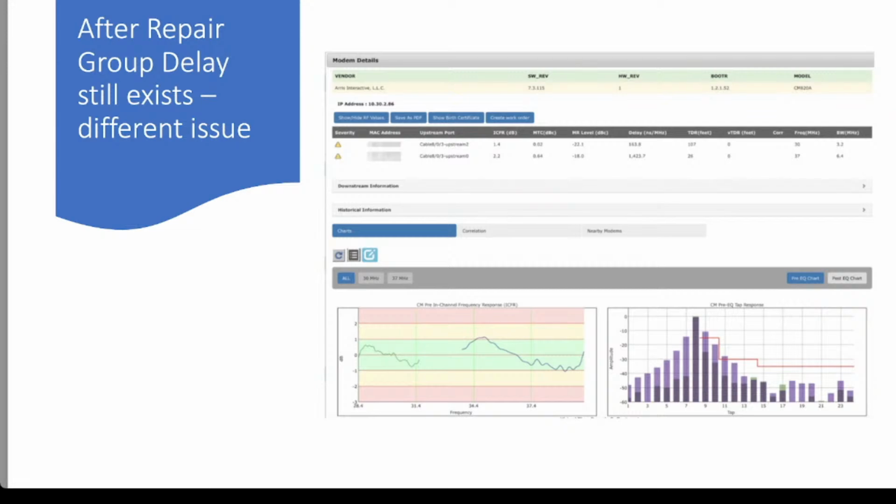Yeah, there's some built-in filter alpha in the channel itself, but you're still going to get some delay and some roll off. So sometimes you won't see the roll off, so the in-channel frequency response will look nice and flat, but there's still time delay because of your LRC, which is inductor, resistors, and capacitance. That circuitry is going to cause delay.